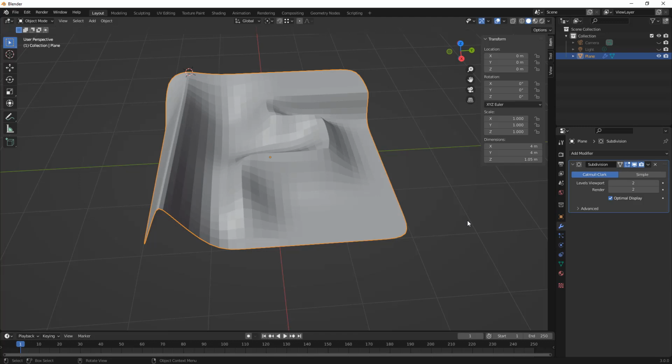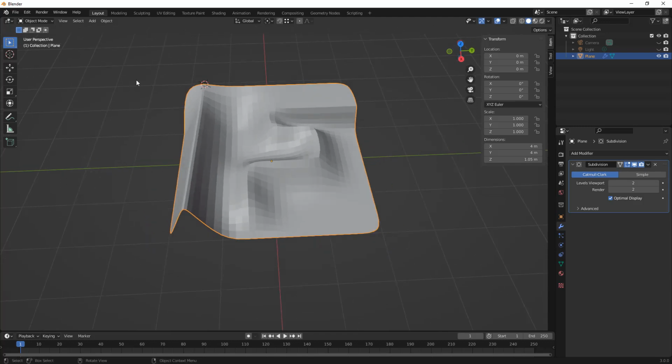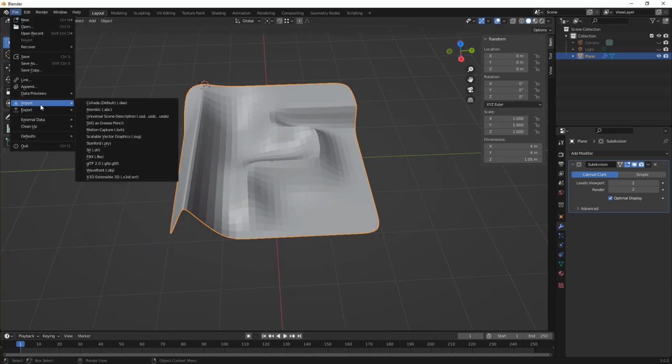The last thing that I'm going to do with this example is I am actually going to export it as an FBX. And the reason I want to do that is so I can bring it back into Fusion 360. And when we look at this, we have FBX and we have STL. Now, I know recently Fusion 360 has been working on OBJ, STL, FBX, and the data that goes along with those exports.